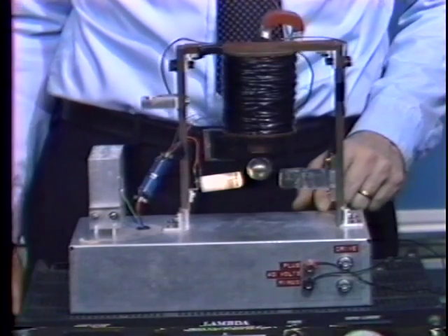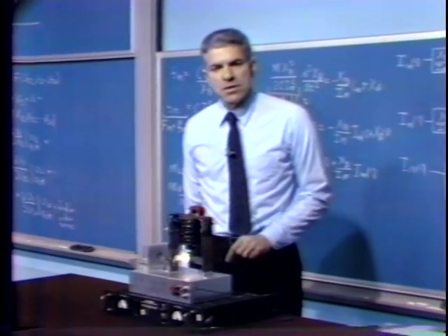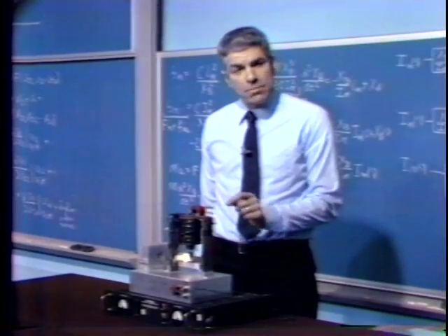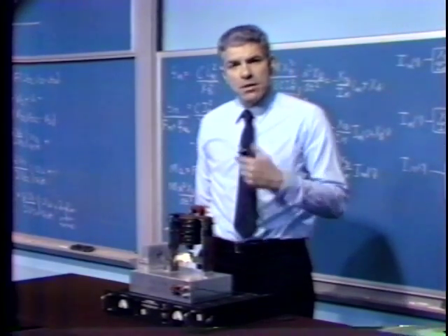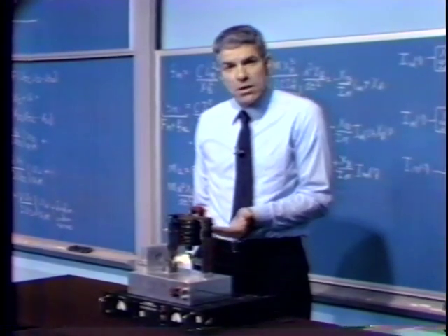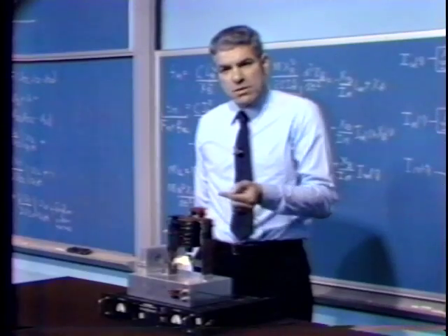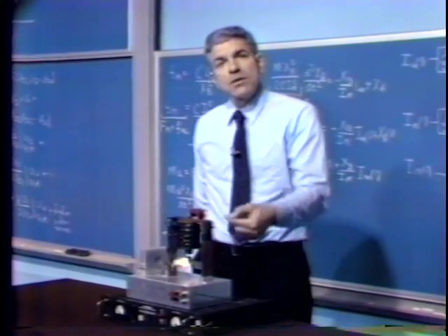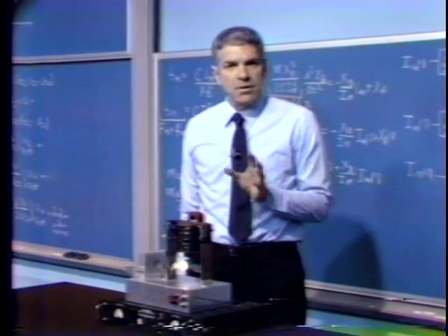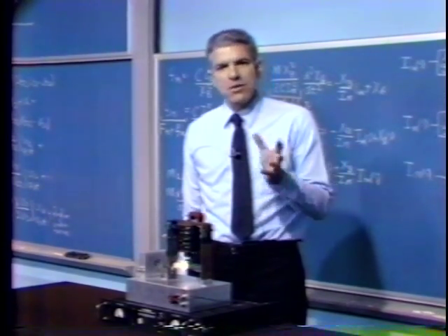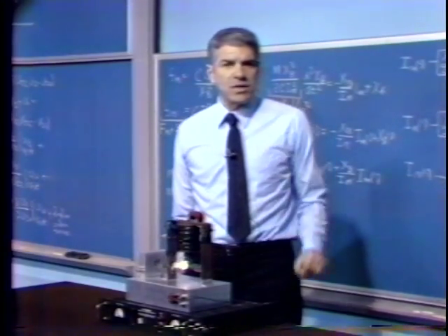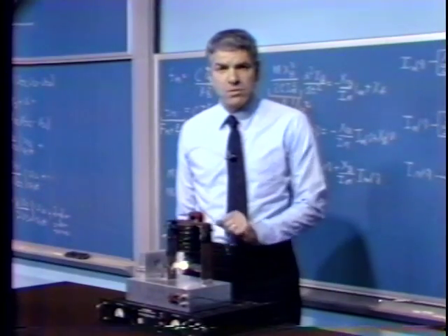So what we're now able to do is measure the step response of the system. The ball's in the magnetic field, we can perturb magnet current just a little bit, and the loop should react. If we increase magnet current, the ball will move a little bit closer to the magnet. As a consequence of that, the loop will react to lower magnet current to reestablish equilibrium. And we can observe the nature of that transient response. It's the usual sort of wiggly, second-order looking kind of transient response that we've seen in a number of other systems, once the system's stable.